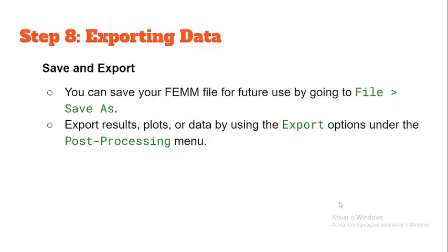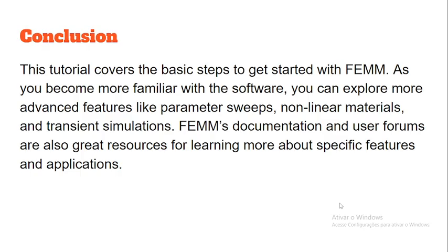Step 8. Exporting data. Save and export. You can save your FEMM file for future use by going to File, Save As. Export results, plots, or data by using the export options under the post-processing menu.